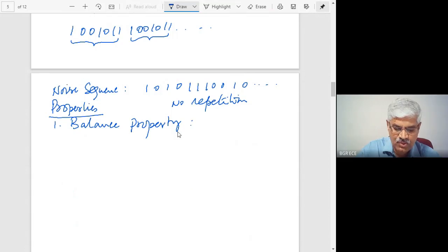And now we can show that this PN sequence that we are dealing with is a small one, of length 7. In this case, the length is equal to 7. It repeats only every 7 bits. These 7 bits, if you look at them, also satisfy this property. Out of 7, there are 4 ones and 3 zeros.